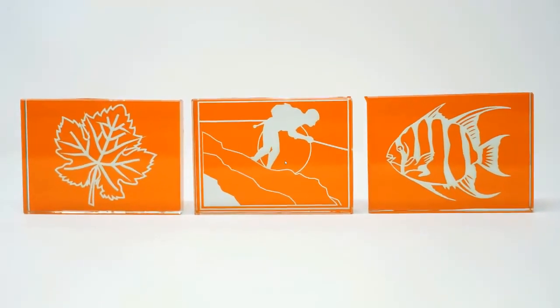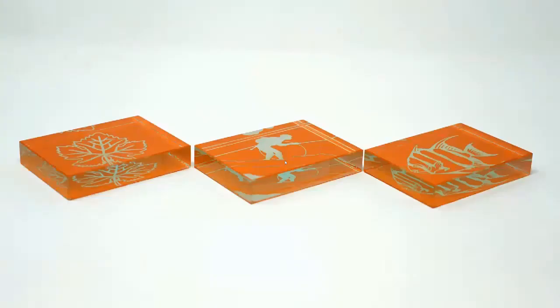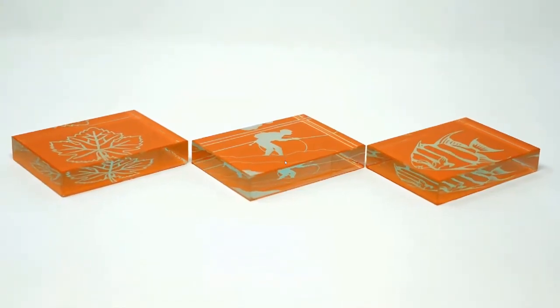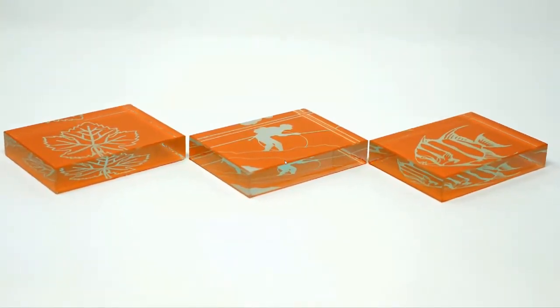So we now have our finished masks ready to go. These are now ready for sand carving. And then we have the ability to take them and put them through the sand carver as they come out of the laser system. So that is the process that is done on the laser side. Simple application of the mask, peeling of the film, and then in turn, sticking them in the laser. Don't forget to focus, use the settings that I just gave you, and then engrave into the material through the mask, and then expose the glass, basically getting it ready for sand carving.